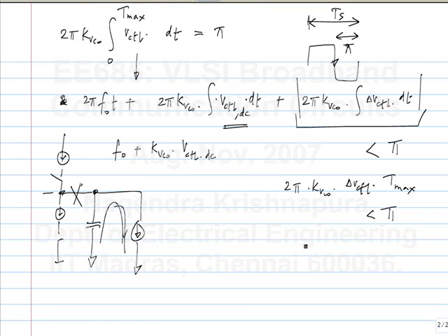So then again you can figure out, what is the V control in that case? That is the leakage current divided by C, times dt. So you will get some square function of T max, and you can calculate T max such that the phase drift is less than a certain fixed value.